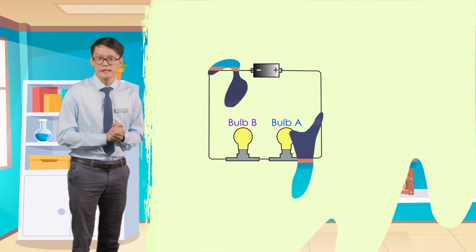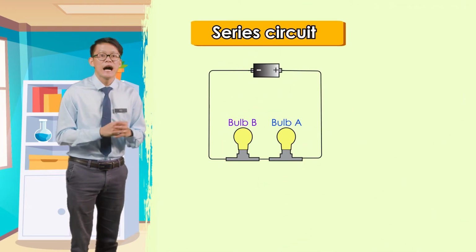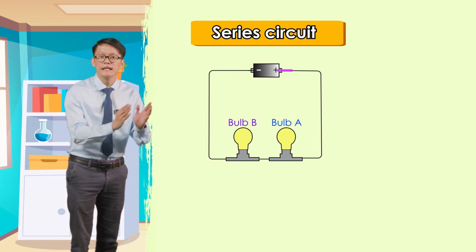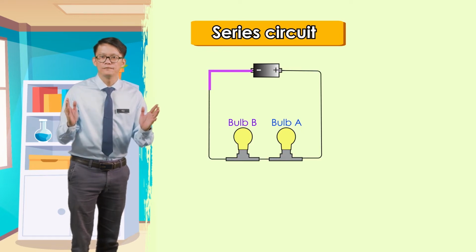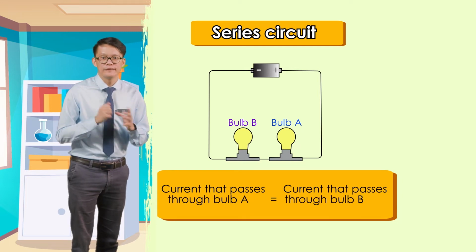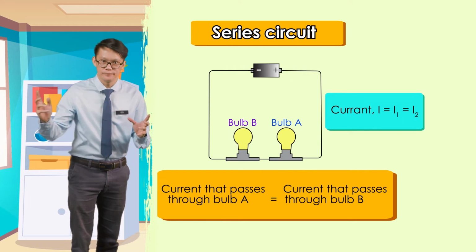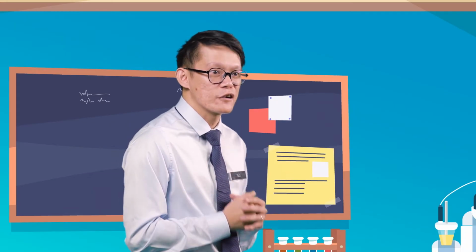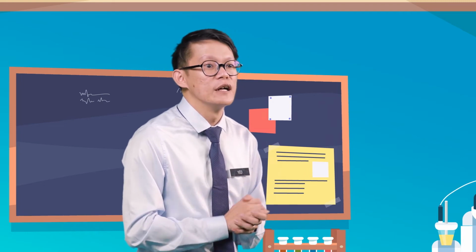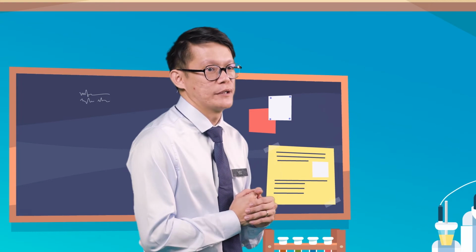For your information, the electrical components in the series circuit are connected along a single electrical path, and each component has the same current through it, which is equal to the current through the network. The voltage across the network is equal to the sum of the voltage across each component.